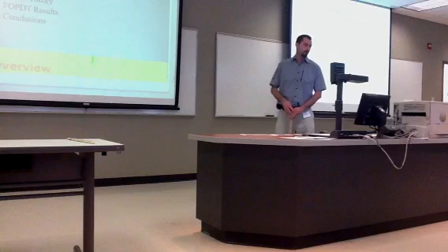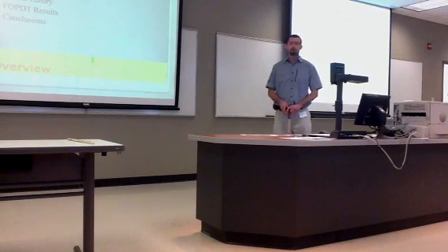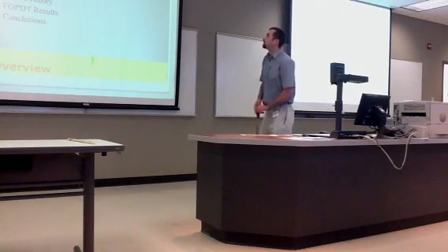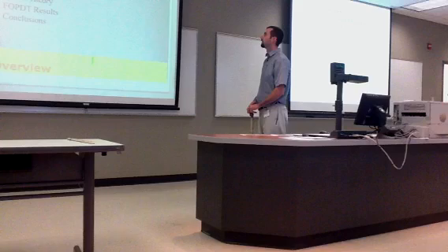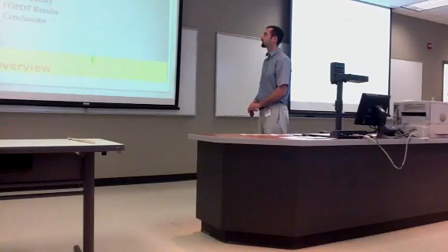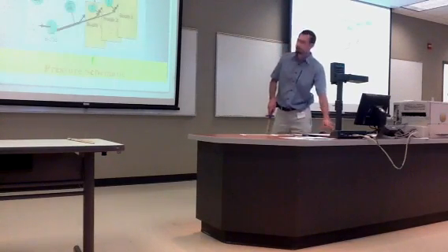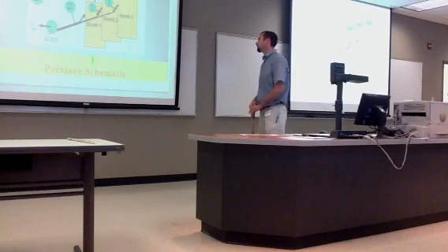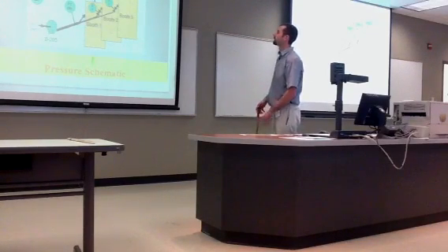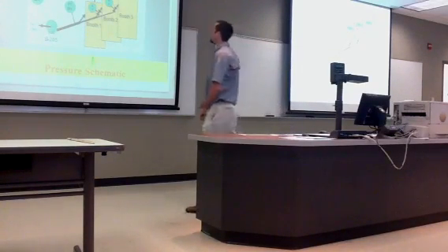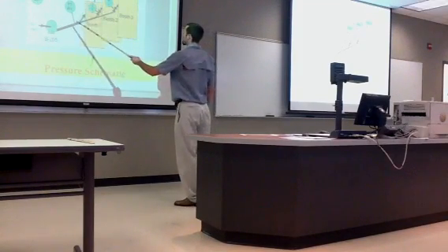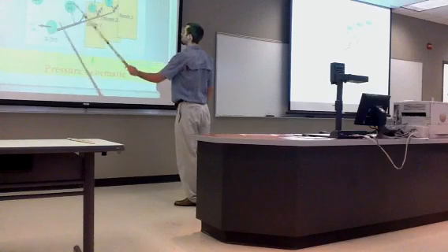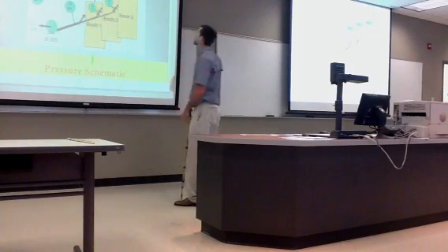Overview is a schematic of the system, the result of the steady state operating curve, the FOPDT, which is first order plus dead time, model theory, FOPDT result, and conclusions. The schematic is of the pressure system along with 3 boosts. We have the pressure sensor, which relays back to the computer and gives us our results.